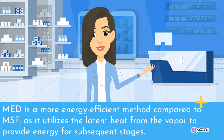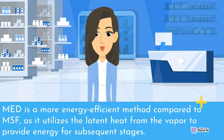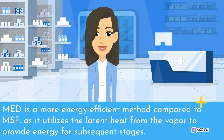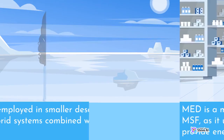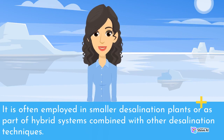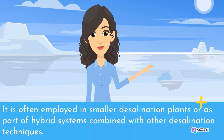MED is a more energy-efficient method compared to MSF, as it utilizes the latent heat from the vapor to provide energy for subsequent stages. It is often employed in smaller desalination plants or as part of hybrid systems combined with other desalination techniques.